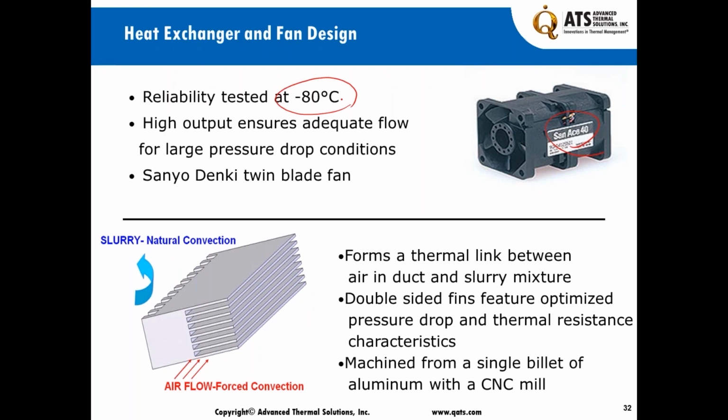It has a high output because it's got dual fans, and with a very good pressure drop. It's unfortunately a little bit noisy, but from the cooling standpoint and the requirement that we had at minus 70 with 6 hours of operation, we had no choice but to go with a fan that is going to meet the pressure drop requirement.